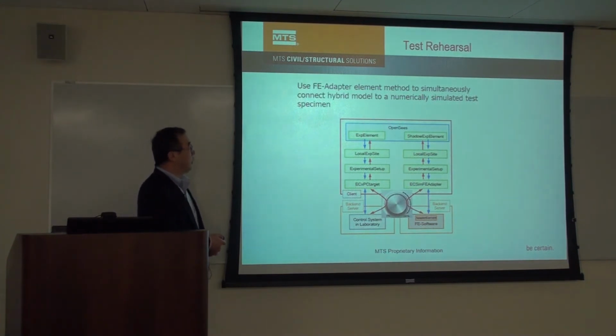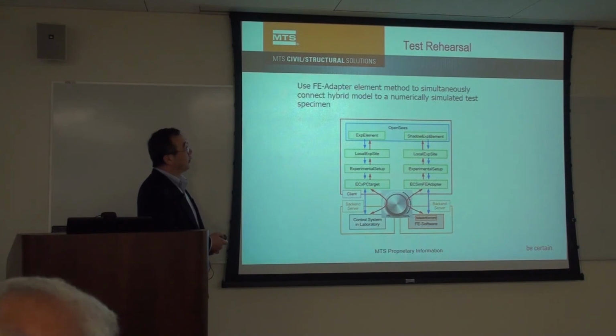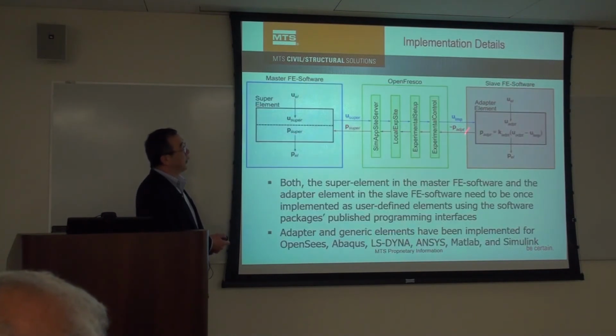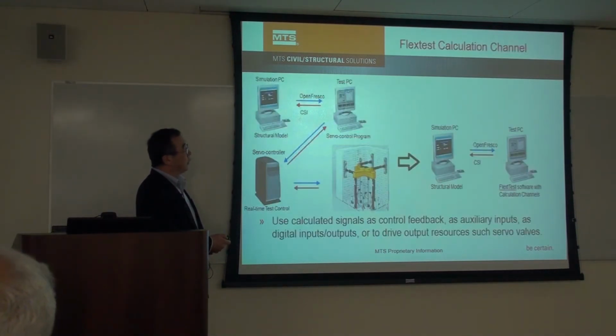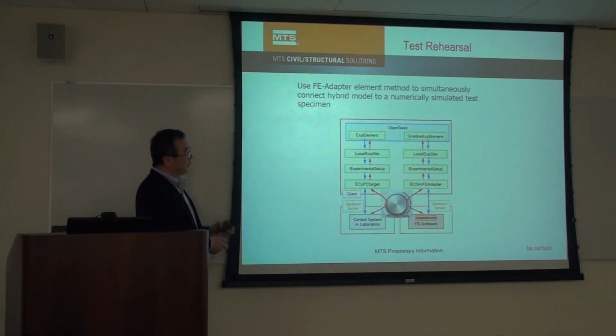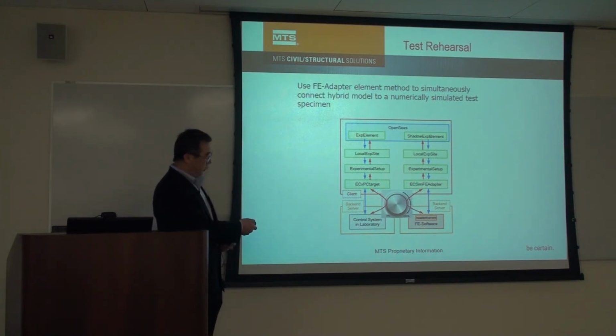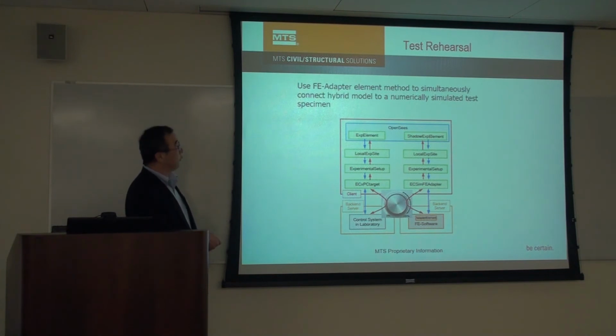The feedback during the test can be from this slave, or from the real test system, and you have a knob here. You can switch, first 100% from the slave, and check whether that is stable. Then 10% from the test and 90% from the slave, and you can adjust this knob, and finally 100% from the test.